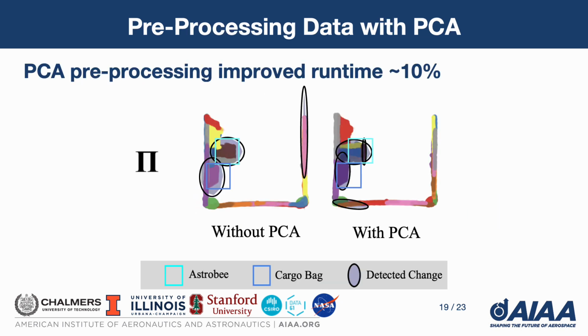In another experiment, the data was pre-filtered with principal component analysis to remove a dimension of the point cloud data and improve runtime. With the Granite Lab, since the z-dimension is practically uniform, PCA essentially flattened the data along this axis. In experiments using reconstructed maps, this step reduced runtime by about 10%, but may not be feasible in more complex environments, such as the ISS.